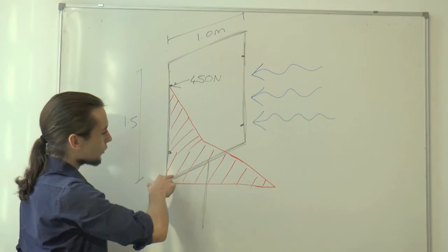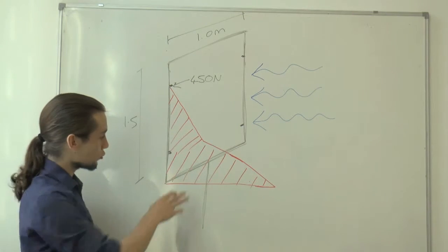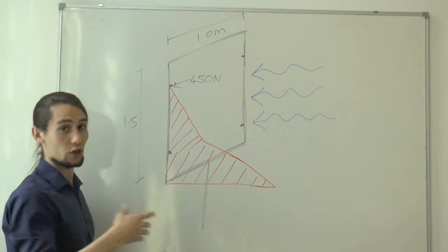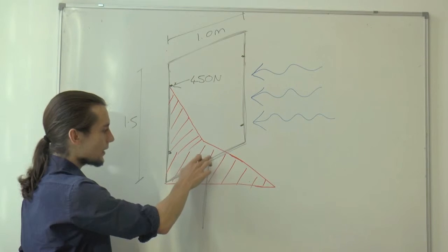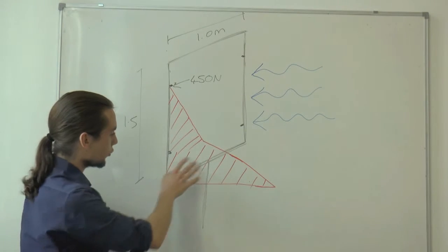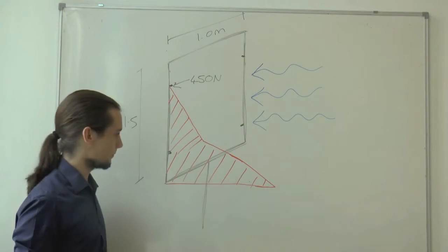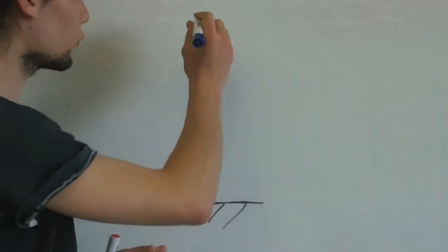And now let's think about what's going to actually happen on the horizontal, and how that's going to be transferred to this column. What you're going to see is some torsional effects in this column, and they're going to actually transfer the load to the column as a concentrated moment. So finally, let's look at this column by itself. We've already got that concentrated moment,